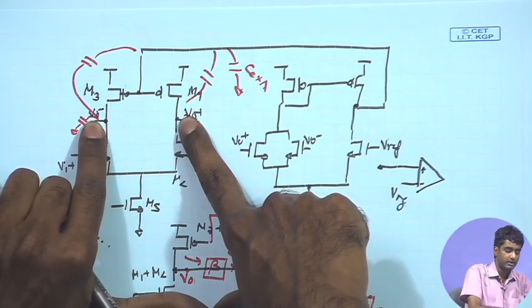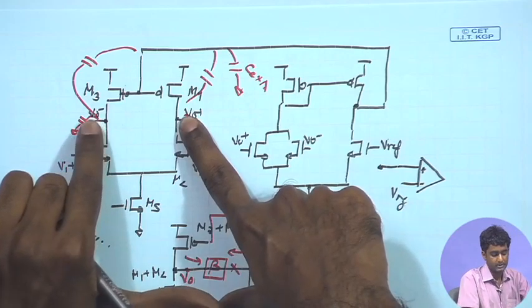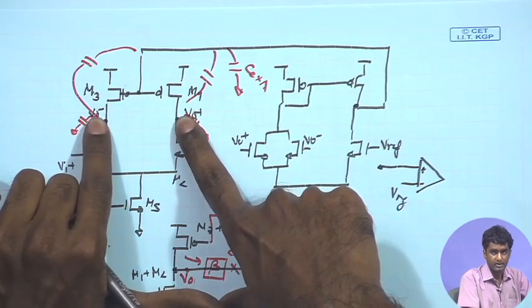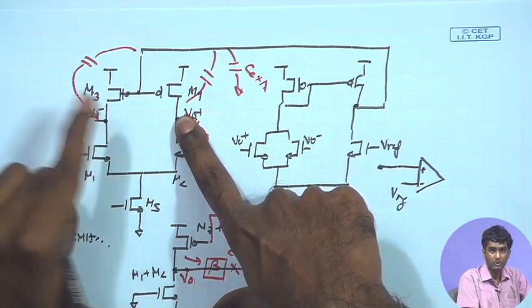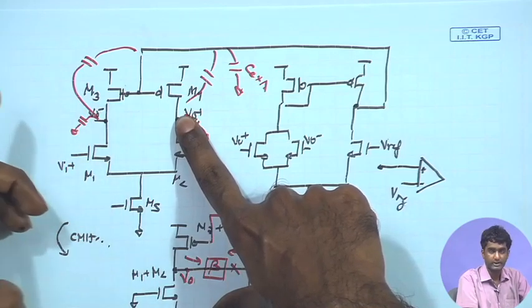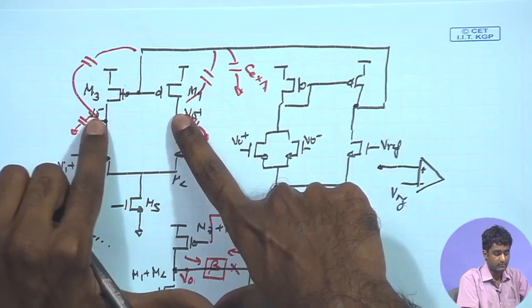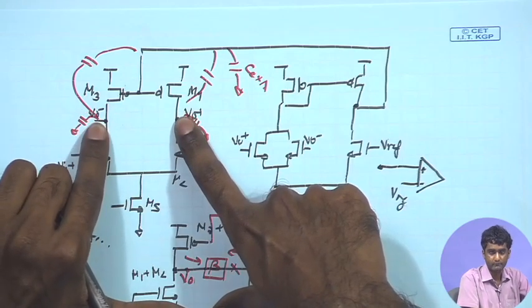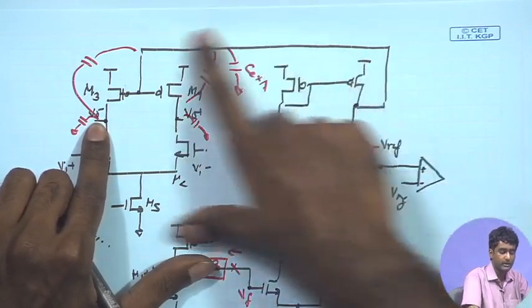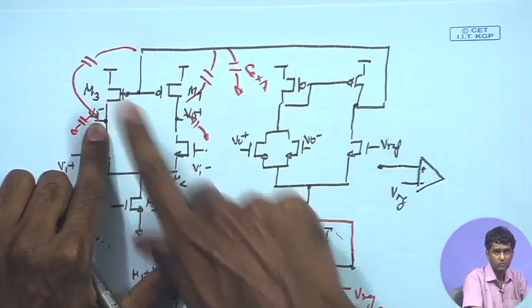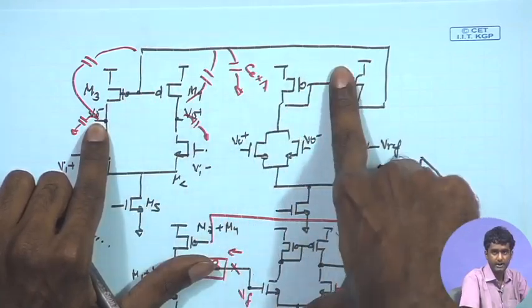For the common mode here, we are assuming that the main concern is the DC point. There is no significant common mode signal as such which we are trying to cancel out. The main concern is to establish a well defined common mode DC point, and for that we do not need to really worry about the bandwidth of this loop or the speed of the common mode feedback amplifier.